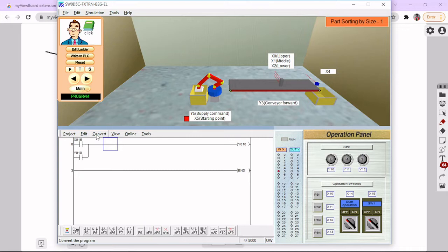So here, this is the latching operation. This is one way to latch. Now the push button X10 is a push button. When I press it, the contact goes back open. But because here I've put the Y10, which is the output, and I've latched it as an OR branch to this run, once Y10 is energized, Y10 here is showing as a contact, as an input contact. So at that time, it will equally be energized, and Y10 will stay energized.